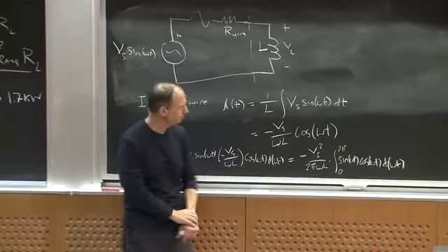What I am doing, however, is not absorbing power on average, but I do have current, right? There's current going into the inductor and there's voltage on the inductor, so I do have some energy transfer instantaneously here. What I have is a sort of slosh of energy from the wall into the inductor and from the inductor back into the wall, okay? But no loss as long as I can ignore our wire. That's what's known as reactive power transfer because it's a reactive component, okay?